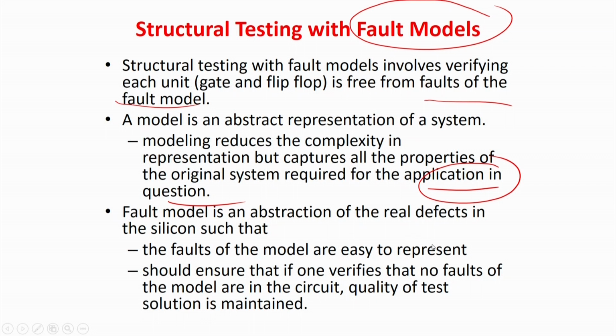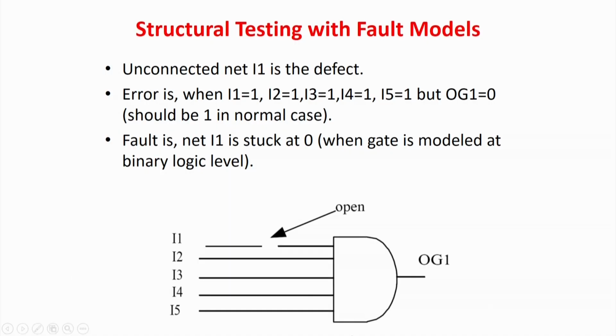So, a fault model is an abstraction of the real defects in the silicon such that the fault models are easy to represent. I cannot give high complexity fault models so that you take years to generate the test patterns, and a huge number of test patterns being generated is also not allowed. It should ensure that one verifies that no faults of the fault model are there in the circuit, and the quality of the test solution is maintained. If I somehow verify that no such faults of the model are present, then quality is more than 99.9%.